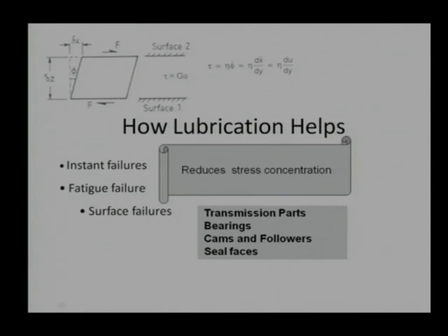That means whatever shear stress is generated in a liquid will be less than 0.1% of the shear stress generated in solids. And we know if the shear stress generation or shear resistance is much lesser, the interface will glide, it will move smoothly, it will reduce the coefficient of friction, and subsequently it will reduce the wear. In other words, whenever we provide lubrication, adhesive wear is going to come to almost zero value, or the adhesive coefficient of friction will come down to zero. I can't say the same for other mechanisms. For the abrasive mechanism, yes, it will reduce, but not come to the zero level.